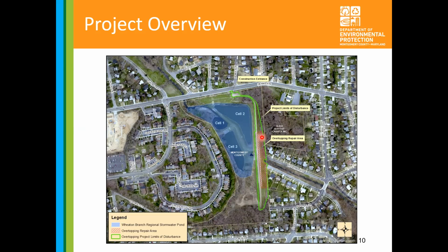The spillway has never seen any flows, and it was designed to carry this probable maximum flood only. The 100-year flood is much lower than this elevation. But an earlier assessment concluded that the dam could fail should the flow reach this level and go down this slope, because this Inca mat and the gabions apparently did not provide sufficient protection.